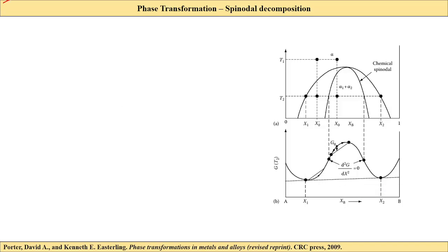We find the ferrite and cementite in laminar structures. So how do they look? They look like this. So this is my pearlite, then this will be my cementite. These are the different structures we have seen. We have pearlite of alpha and Fe3C.